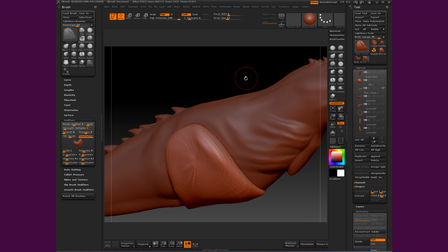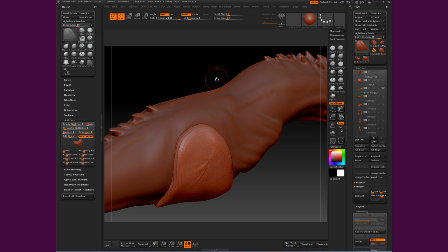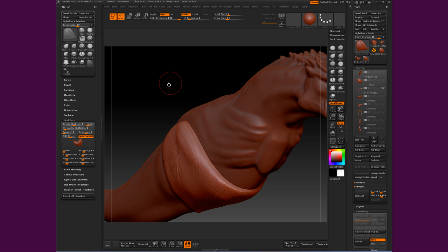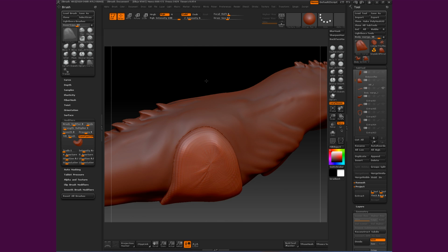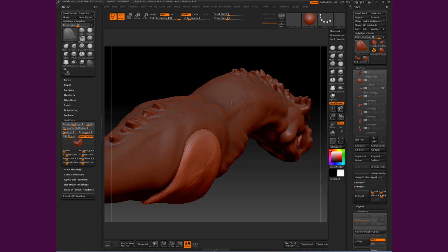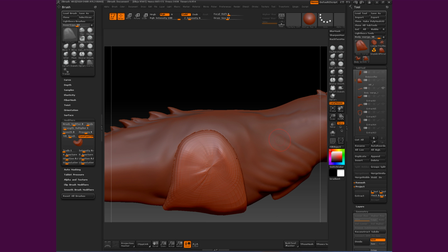A couple of things that I ran into, and that is if the mesh brush object that you use for the mesh brush is a Dynamesh, it does an AND, which is the middle piece, instead of either doing a union or a subtraction. I'm not sure why that is, but yeah, keep it as a non-Dynamesh piece and you should be in business.